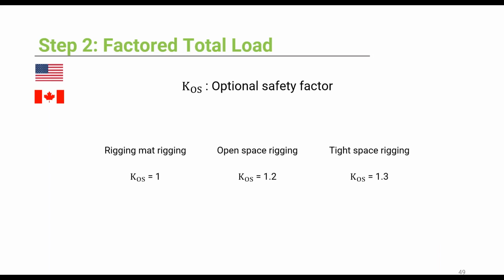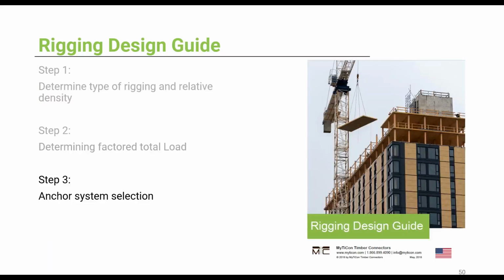And kOS, which is our optional safety factor, depends on the rigging situation, whether you're doing your rigging in an open space or a tight space like a downtown area. After the factored total weight is calculated, the right yoke anchoring system can be identified.